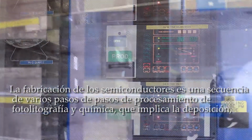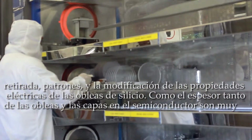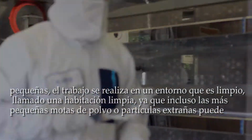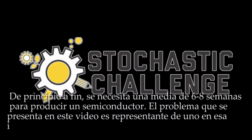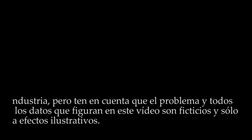The fabrication of semiconductors is a multi-step sequence of photolithographic and chemical processing steps involving the deposition, removal, patterning, and modification of electrical properties of silicon wafers. As both the thickness of the wafers and layers in the semiconductor are very small, the work is performed in an environment that is clean, called a clean room, as even the smallest speck of dust or foreign particles can render the device unusable. In addition, numerous electrical tests on the devices are made at each of these steps to ensure proper performance. From start to finish, it takes an average of 6 to 8 weeks to produce a semiconductor.